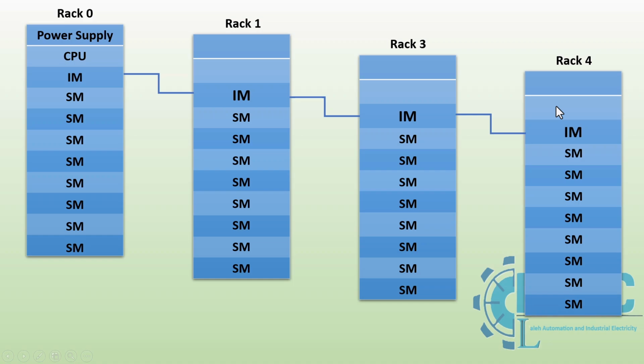In the hardware configuration within Siemens Step 7 software, if there is no expansion rack, we must leave slot 3 empty in the configuration. However, in real hardware, all modules must be physically connected without any gaps. If I don't need to use an expansion rack and only have 1 rack, how many modules can be placed in this rack? Please leave your answer in the comments.